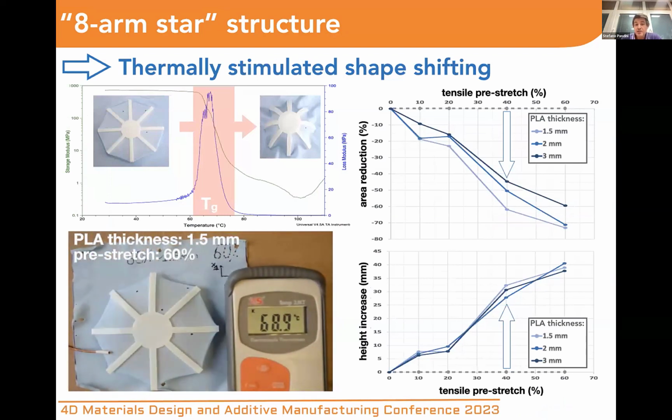And so interestingly, the material does not change its shape until the transformation temperature is approached and undergoes a change typically in 10 to 30 seconds. And this suggests the possibility to store the printed material in a flat configuration and activate the shape changes by a highly specific thermal trigger, somehow like the pasta we saw before.